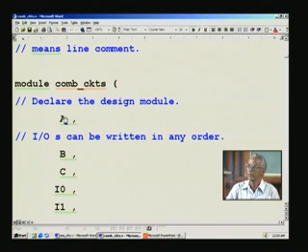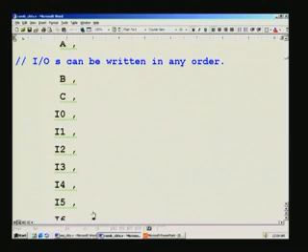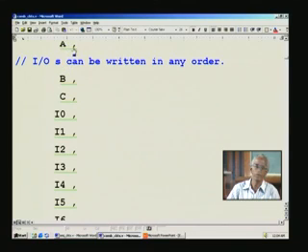And we have already seen here, we had to declare the design module. That is what is being done here. This is the module name that we give, and that is how we declare it here. And what appears here, A, B, C, I naught and so on, note that every input is followed by a comma, just to indicate that this is one signal, another signal is this, just a comma separates one signal from the other.